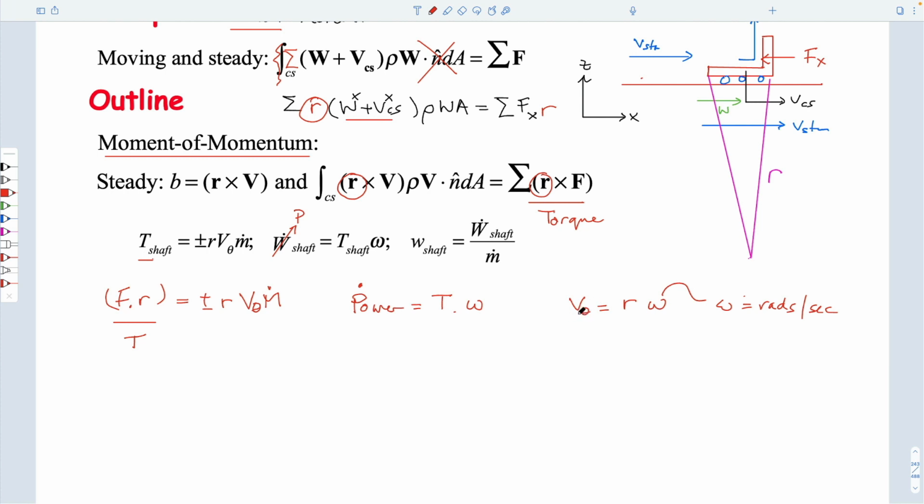So this is a velocity of the system, which I'll draw, which I guess I should have drawn. And 2 pi radians a second equals 2 pi omega equals rotations RPS. So sometimes you want things in RPM, rotations per minute, rotations per second. This rotation is dimensionless. Radians per second has no dimensions. Has 1 over seconds as dimensions. And multiplied by a length is a length times 1 over seconds is a velocity, which is v theta. So take that on trust.